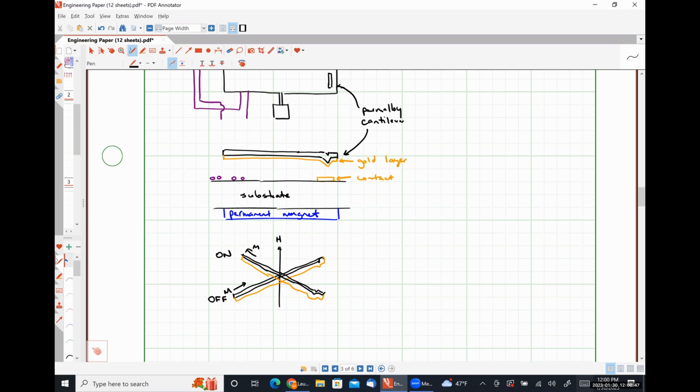And if you're switching states, in addition to mechanical deformation, you're talking about high voltage potential; could we potentially pull apart as you're closing distance? So you could, that's called stiction, you could deal with as well. That would be effectively like welding the contacts closed. That is also a possibility. That's going to be true of any type of mechanical switching you have at the MEMS scale. There's always the potential for stiction as well. So the electrical contact gets made and it welds the two materials together.